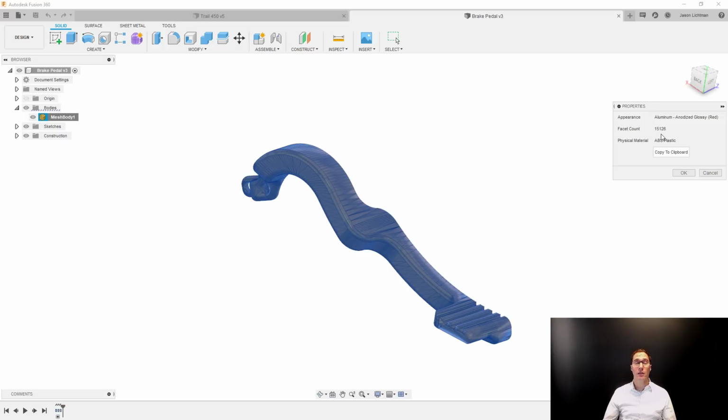This was actually created from a BREP model. I'll just be very direct with you on that. And that's why I have only 15,000 triangles. If I had scan data, this might be closer to 50,000. Depending on the resolution of that scanner, this could be a million or 5 million triangles. This could be a lot. In this case, what I'm looking for is less than 50,000 triangles. In particular, 49,999. That's what my goal is, less than that.